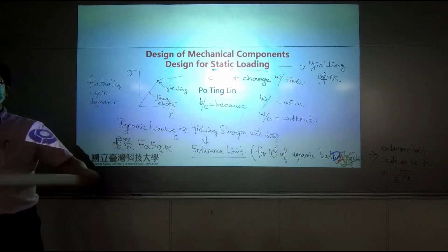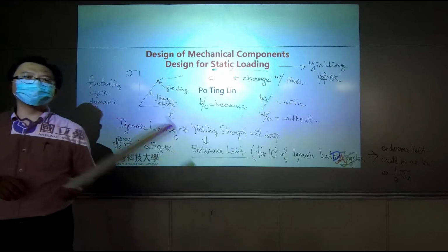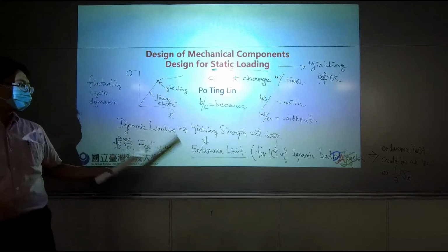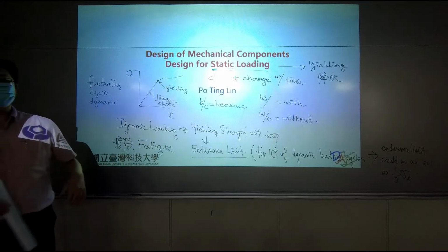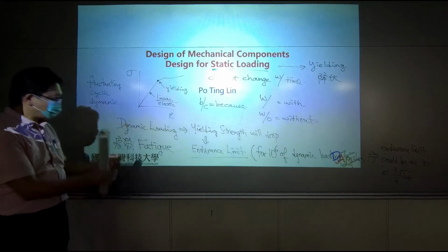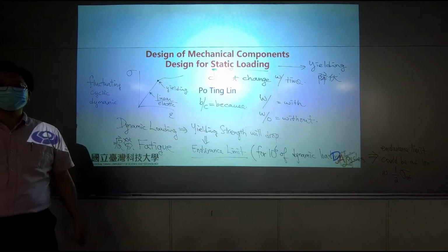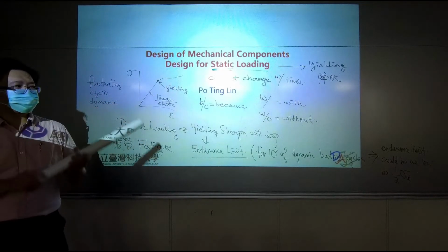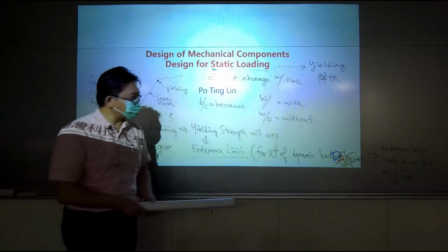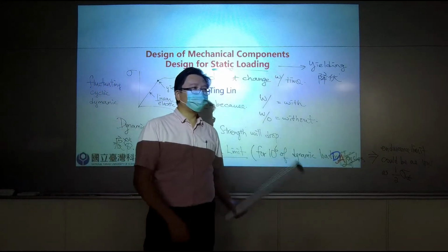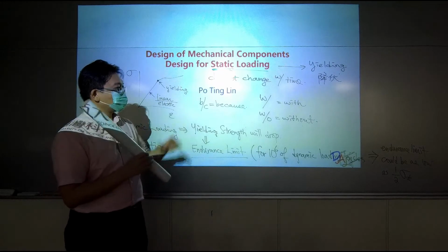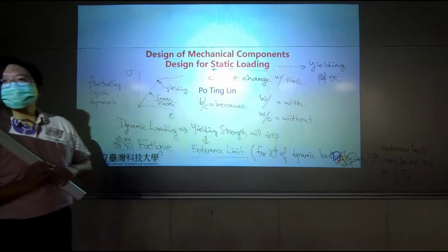So if a material is under dynamic loading, we have to worry about a drop of the strength. And that phenomenon is called fatigue. And the effect of fatigue depends on how many times of the load cycle that you apply to the material. Okay? So, is it okay?